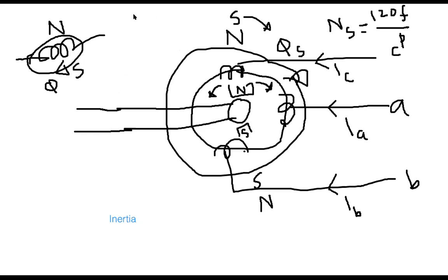What you have to do is put a specific coil. Everybody look, this is the rotor body. On the rotor body, now I put only one specific coil. What is the objective of that coil? Now everybody remember the induction motor principle. Why was the induction motor rotating? Because there were no physical poles, but there were 3 coils. And what happened? This rotating magnetic field caused voltage on these coils. And then there was current flow, there was another flux, there was interaction of the 2 fluxes, and the motor started rotating. So exactly because of the inertia, initially the synchronous motor is not running, so I have to place a coil.